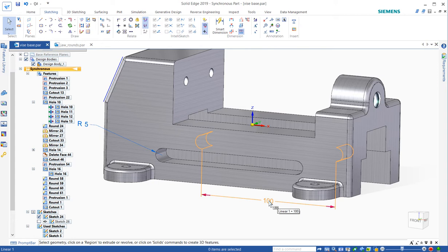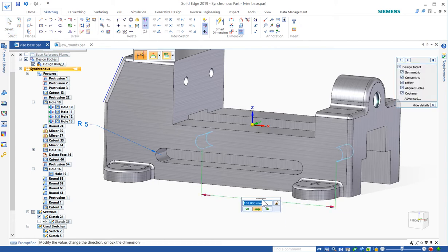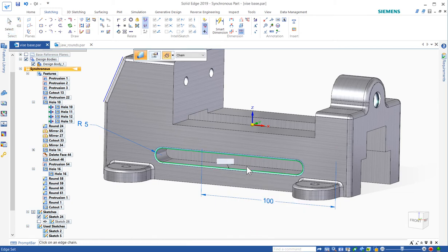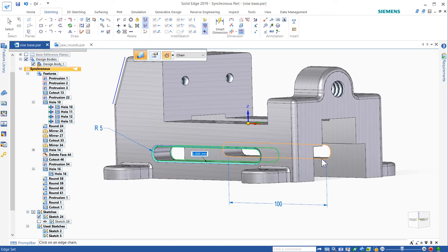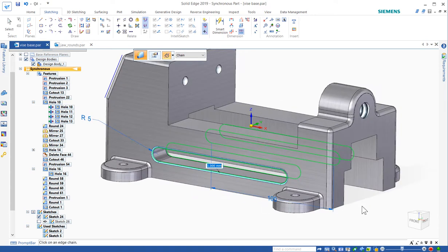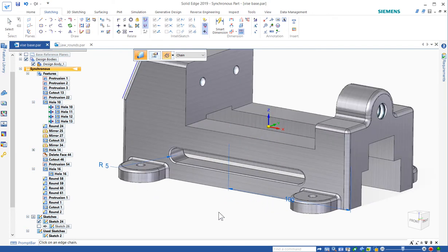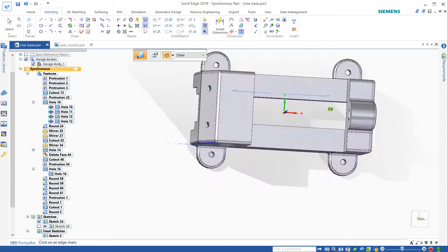And then you'll notice when you come back onto it, even if I do, after you edit the dimension in a particular manner and given it some intent, when you come back onto the dimension, the default behavior, regardless of how you move your mouse, will be that symmetric or left or right or whatever it was that you chose. So that's design intent being stored in the model based on how the model was edited last time. It most likely will edit successfully the next time if you edit it the same way. So a different user, this actually survives across sessions. So if a different user opens this up next Friday or something, they'll get that behavior.